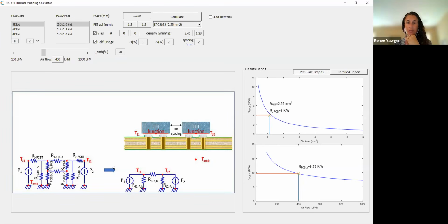How much of a difference would vias in pad with a conductive fill in them make to the thermals? The vias shown so far seem to be non-filled ones. That's right. The diagram is kind of deceptive. It looks like non-filled, but we actually recommend non-conductive fill. So the question is how much improvement if you take this via instead of non-conductive fill, put in conductive fill.